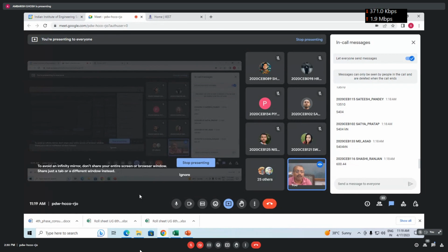Next, we have gone for the pile load test, which is very much important to assess the load carrying capacity of a pile. Cantilever method you have seen, then you can go for dynamic method. And if you look into the pile load test difference, the initial pile load test and routine pile load test, and their merits, demerits, their objectives, and how to get the capacity from the pile load test, that also guideline is there. For that you have to read IS 8009 part 4. Okay, so this is all about pile.